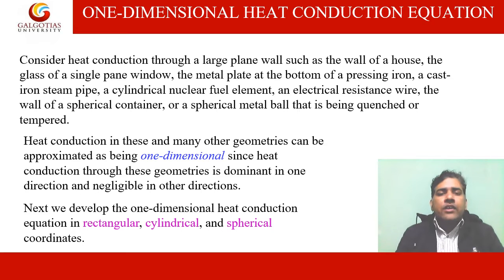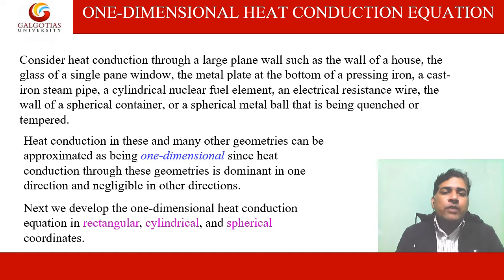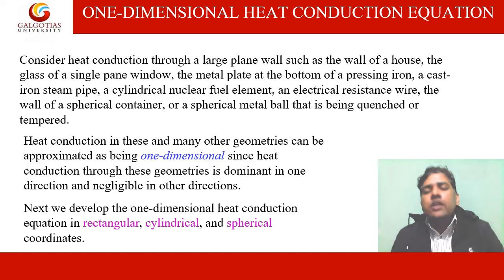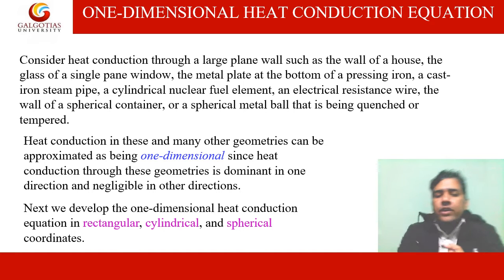One is the heat transfer by conduction from one surface to the other surface, and the other is the heat generated within the body. If we have a body, two things can happen: heat may be transferred from one end to another, and heat may be generated within the body. So these two things should be considered simultaneously for the derivation of the one dimensional heat conduction equation.